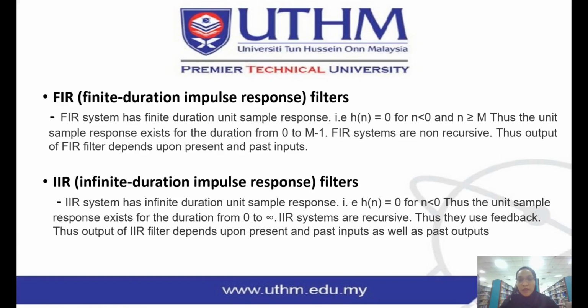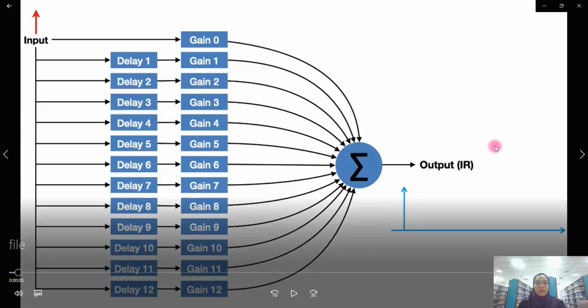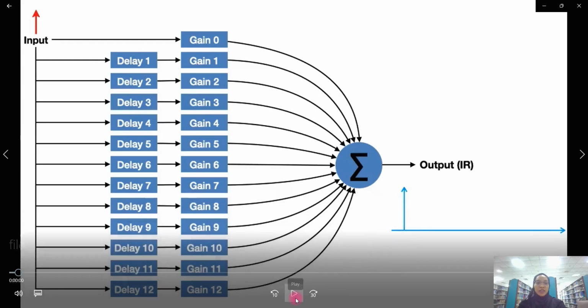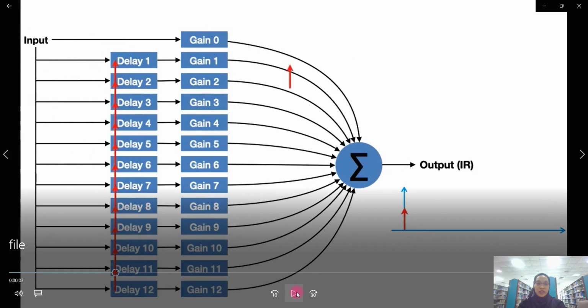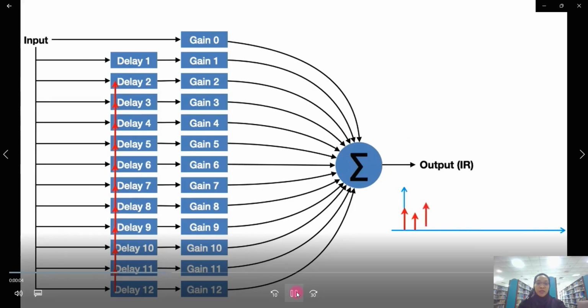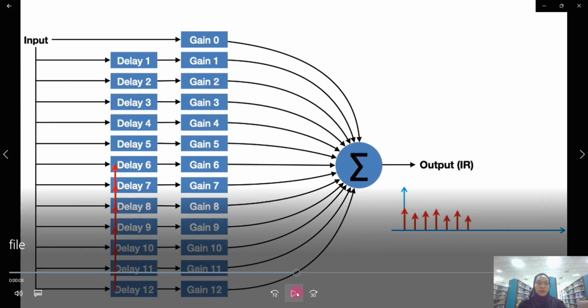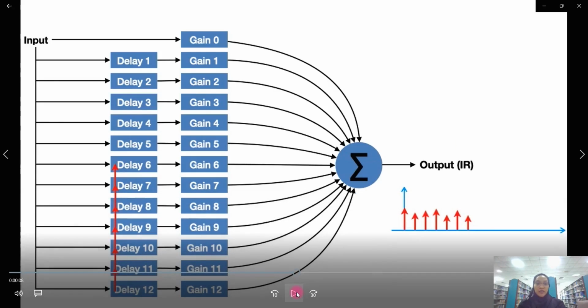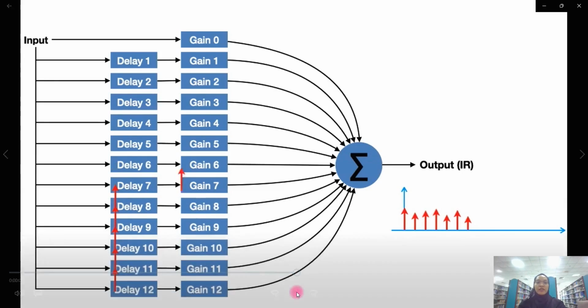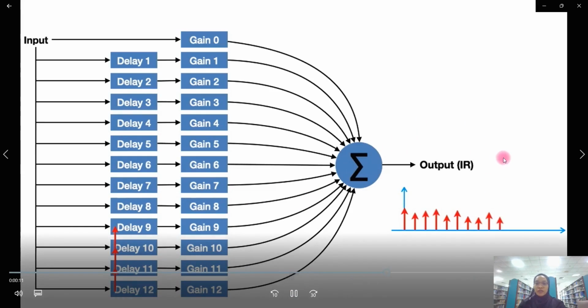For better understanding, I will show you the previous video. The following animation shows the process of how the gain factor is equivalent to the coefficient of the impulse response. The idea of the FIR filter is to connect the input to delays in series. The first has only a small sample delay, the second has two, and so on. After that, an amplifier with the gain factor is set for each delay, and finally the delayed outputs are merged together. So you can see the output is like that.